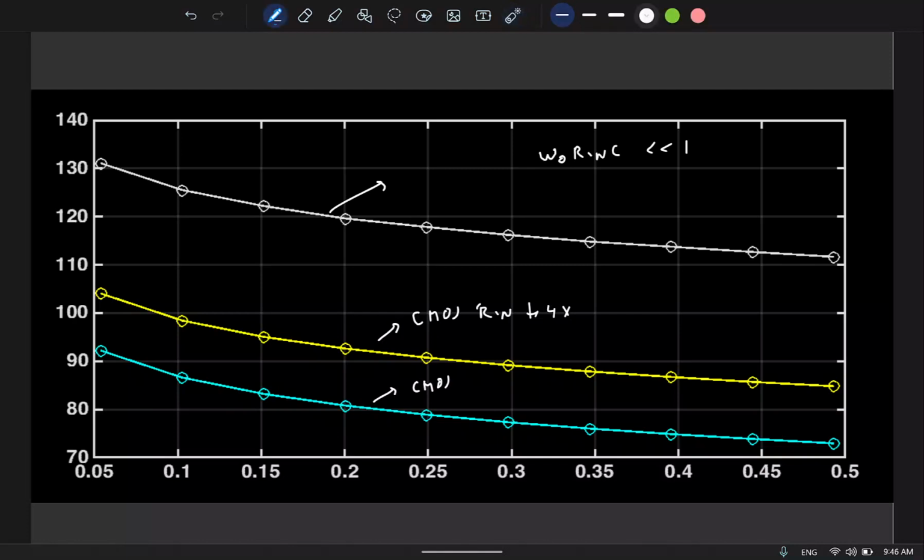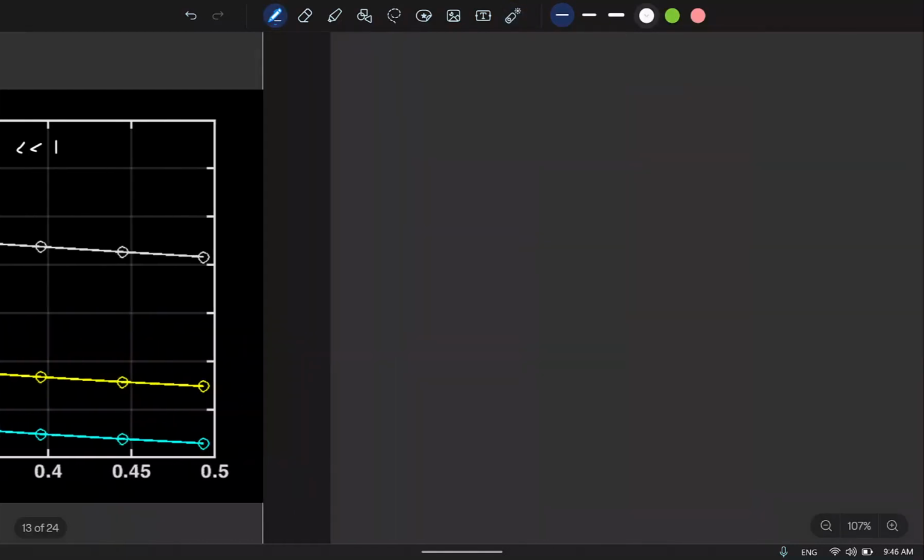Okay, great. So bottom line, we have 4 candidates for switches. One is an NMOS switch, and this is a good switch for held or constant signals close to 0. So it is an ideal candidate if you want the switch to be connected to ground, you can nicely use an NMOS. Similarly, for PMOS, it is a good switch for held or constant signals which is high or close to VDD. So this is an ideal situation for a PMOS.